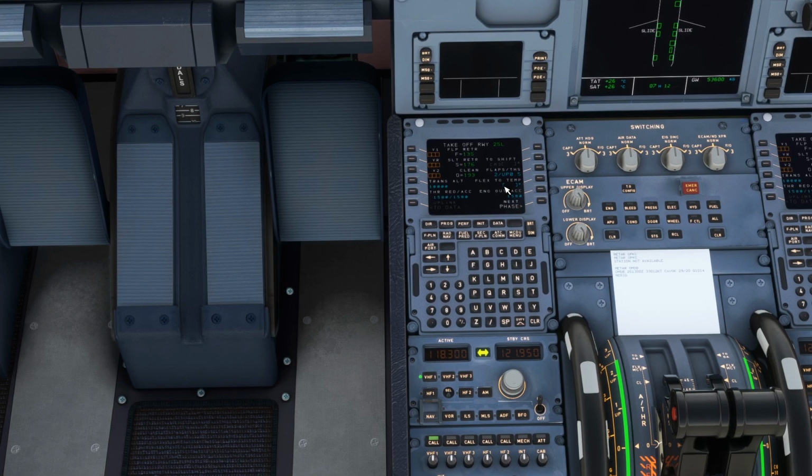Flex to temperature is basically how the plane adjusts the flight management system. You tell the flight management system what the outer temperature is. So let's say the outer temperature is 40 degrees, and obviously a certain power is given to the engines, and you give full power to the engines during the takeoff, the engines might get heated up in higher temperatures, let's say 40 degrees or 45 degrees. So in this, you basically calculate flex to temperature.